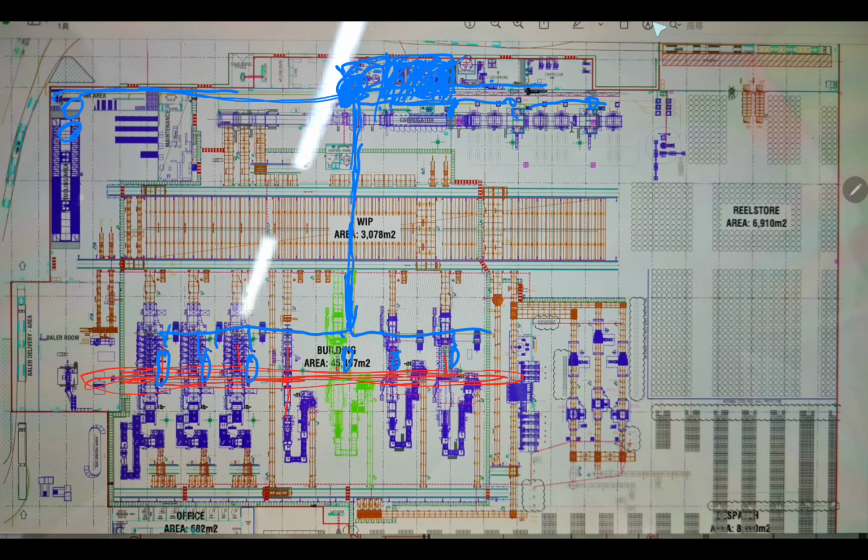The boiler is very dangerous and very sensitive. Find a proper operator to give us proper tests. Every week we need to collect a water sample and check the hardness and the pH, all of these things.